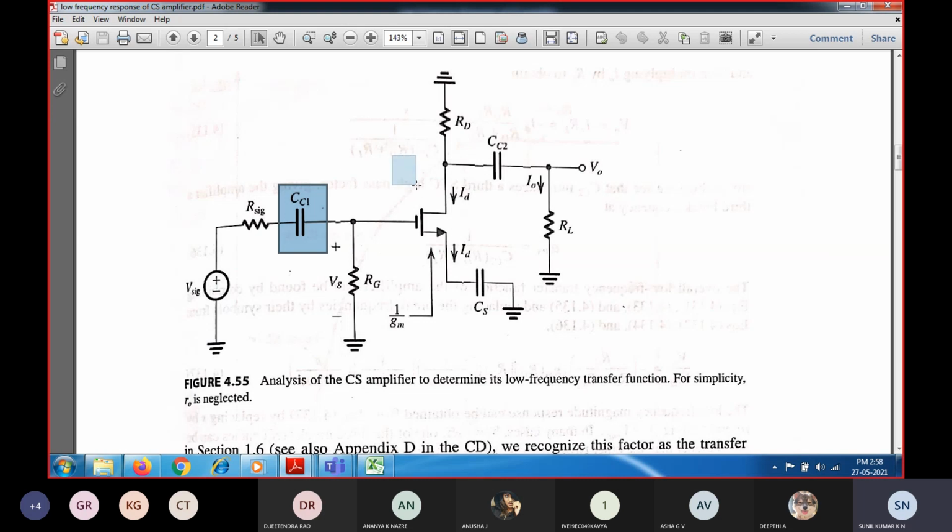So this frequency is very important. Because the capacitance is fixed and 2 pi is fixed, as you increase the frequency, the denominator term increases, and obviously this capacitive reactance is going to reduce. So Xc is equal to 1 by 2 pi f into c. If you increase the frequency, the impedance is going to reduce, because of which it is going to act like a short circuit afterwards.